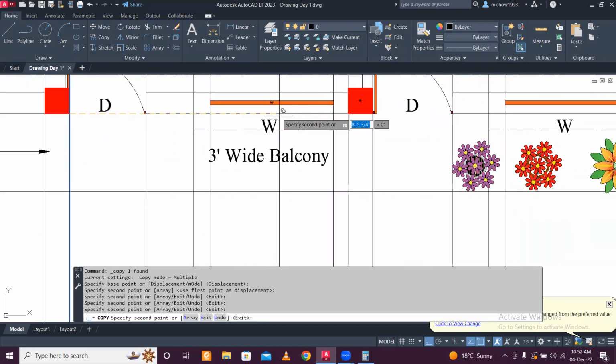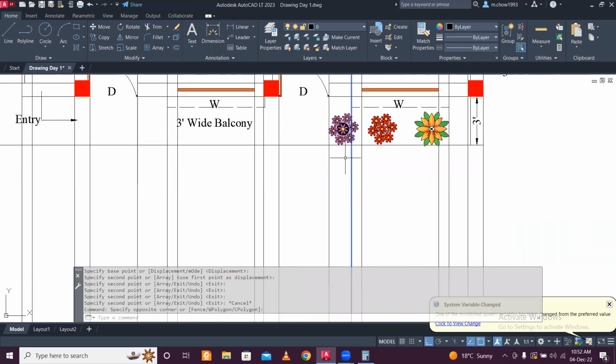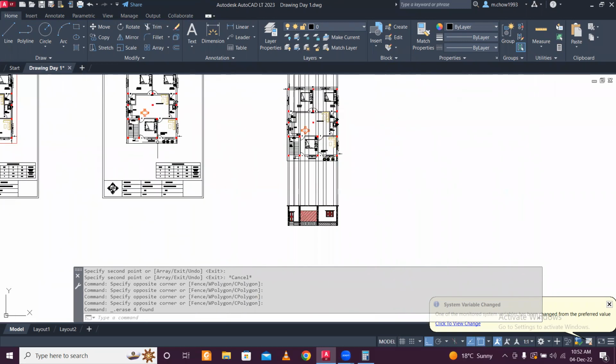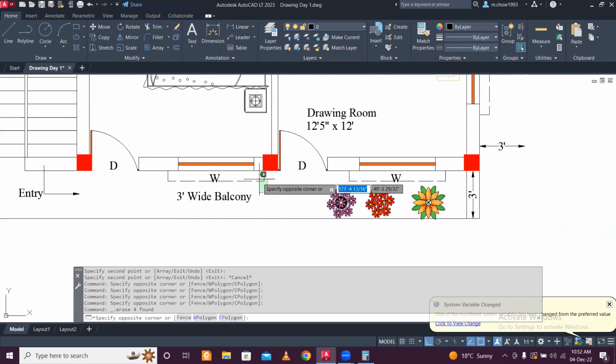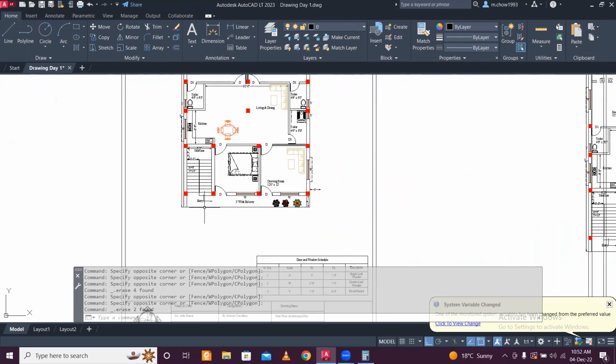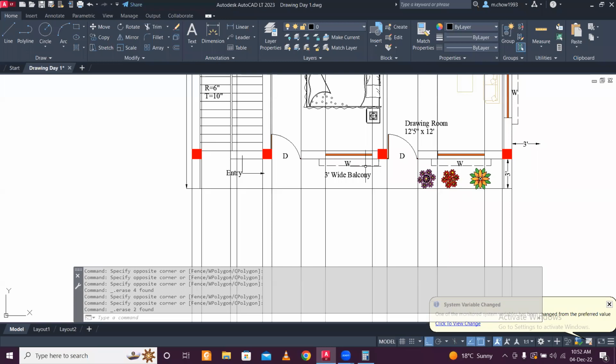Select this and obviously we have the remaining things. Okay, window chaja, no need. Balcony is there, so we don't need a chaja here. So we have to correct this in the plan as well. Select this and select this. We don't need these things. So we'll correct this in the plan. I hope this is not a group here. Luckily, okay, just delete this. We don't need chaja because there is a balcony here. Okay, so this is it, and delete it here as well, but it doesn't matter.